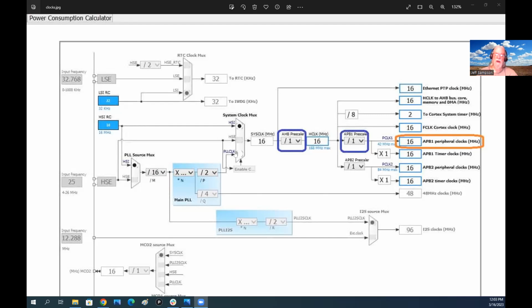And then it goes through here. You have to select the path for the clock coming through into here. Then this tells you what is actually coming out of what this block is generating. It tells you here what it's running at, and I put in numbers, so this said 48 megahertz. And there's a bunch of other stuff you can do here to change what happens out here.